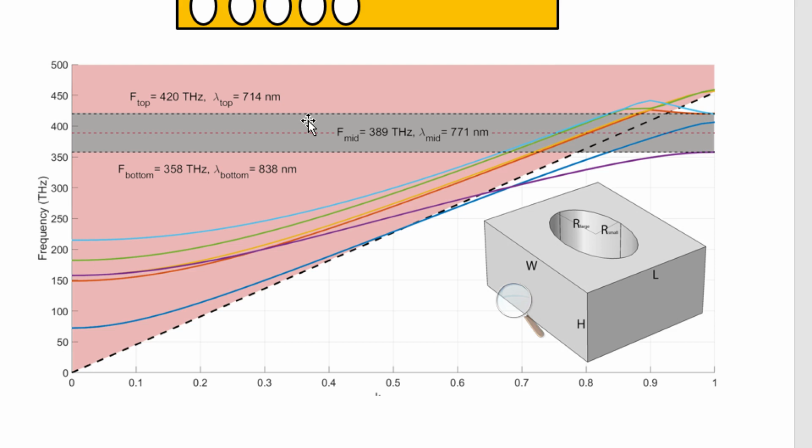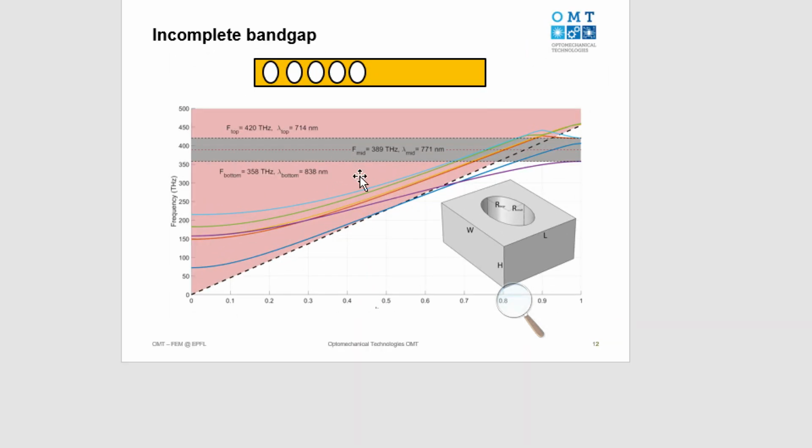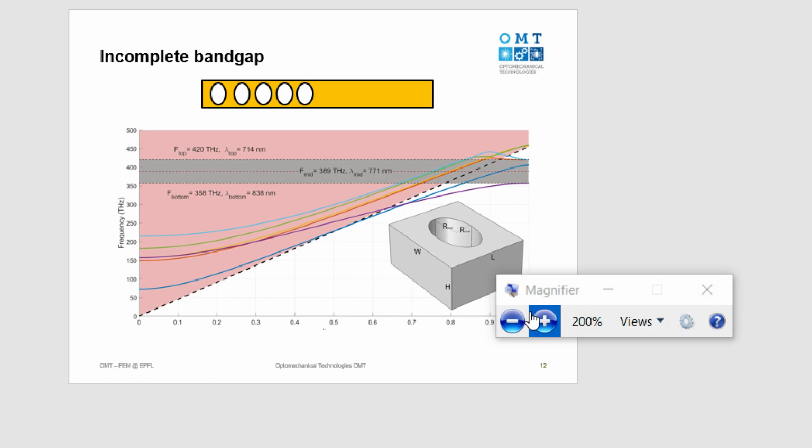Right, so just coming back to what Amir just explained to you guys, for example, if my waveguide here is a perfect rectangle, my TM mode, for example, would be like here, the other one would be like here, so they're orthogonal, so they cannot couple. But if you have some imperfection somewhere and there's scattering, they can couple to each other and you lose your ideality. So with that, I think I'm finished, and if there are any questions, I'm happy to answer.